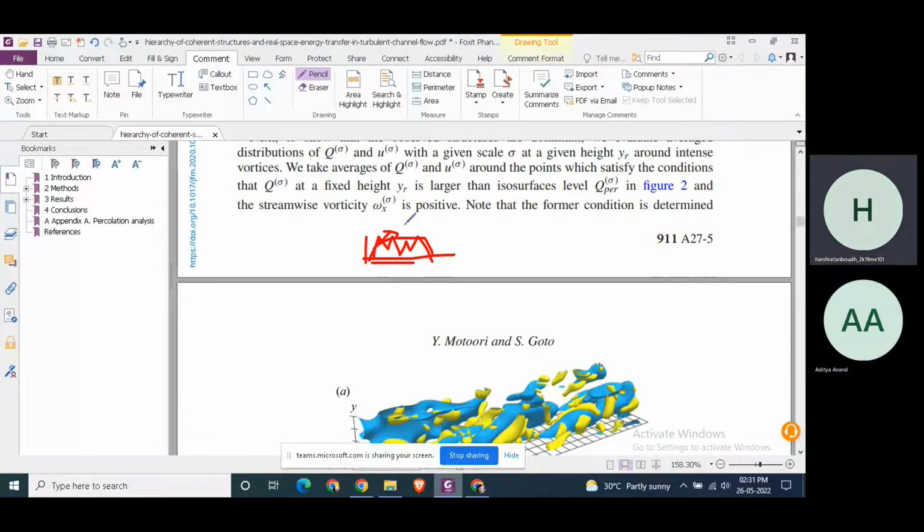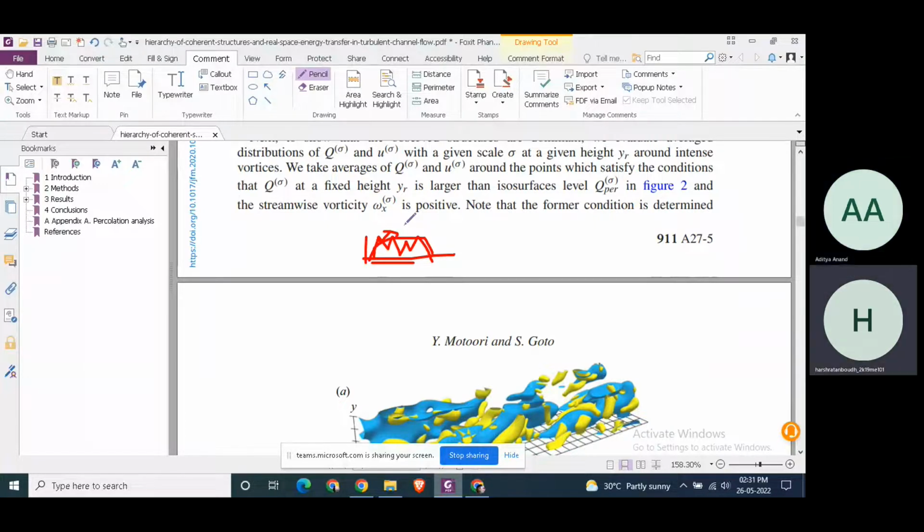Okay, so the mean part is generally responsible for the mean of the flow, like the large eddies, or the large scale coherent structures. It's not necessarily true. If your flow is statistically stationary, your mean will not change. So your fluctuating velocity, the one that you get after subtracting the mean, will have contributions both from the large ones and the small ones. Okay, I did not know that.